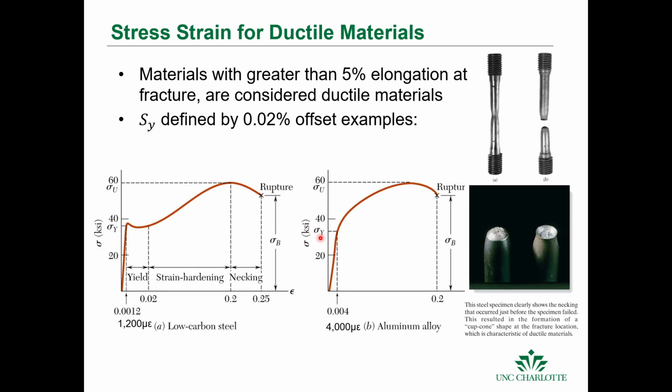The main takeaway that I want you to see is that these materials will behave differently, and so from a design perspective, if those features of that material are important, and you need to know exactly where that yield stress is, or that yield behavior, then you just have to take a look at this and understand that these yield points are just defined differently for different materials.